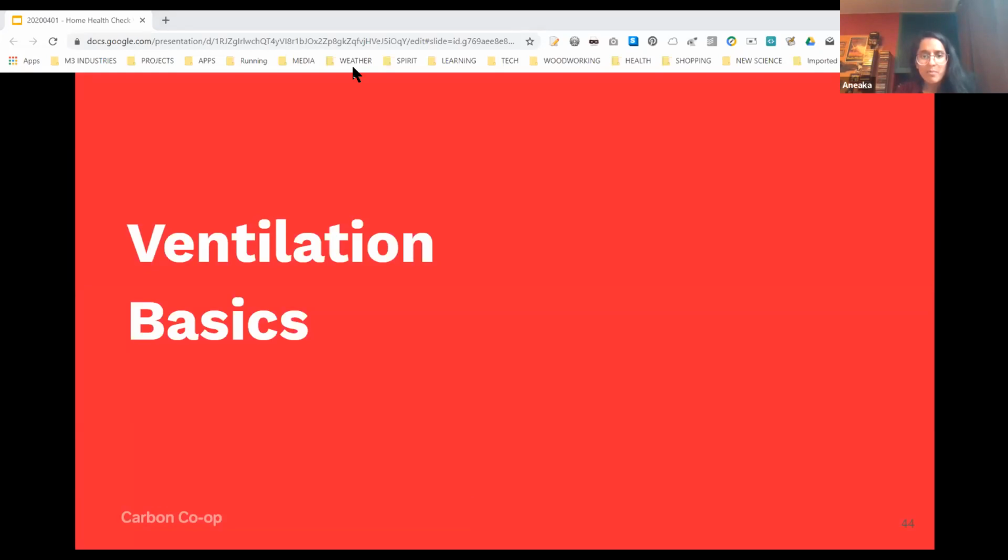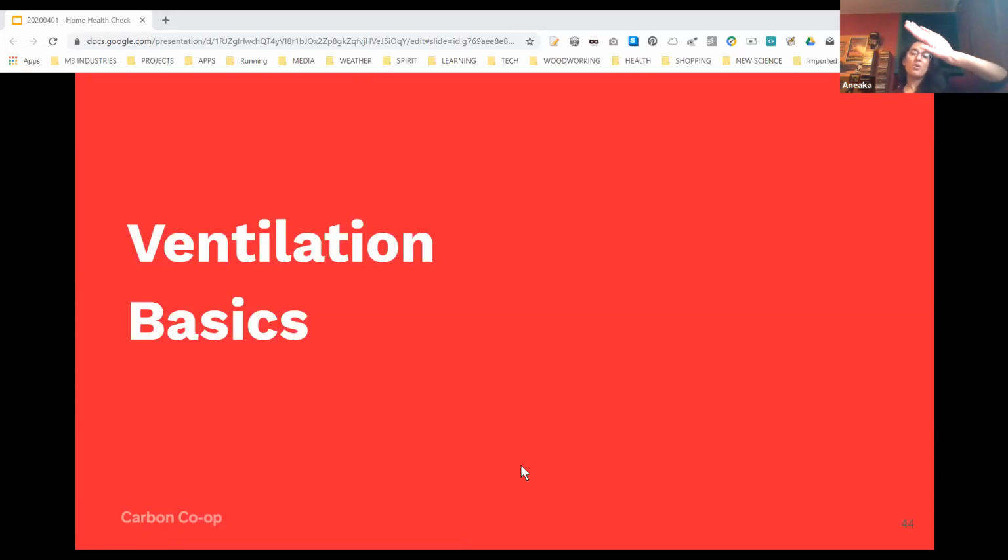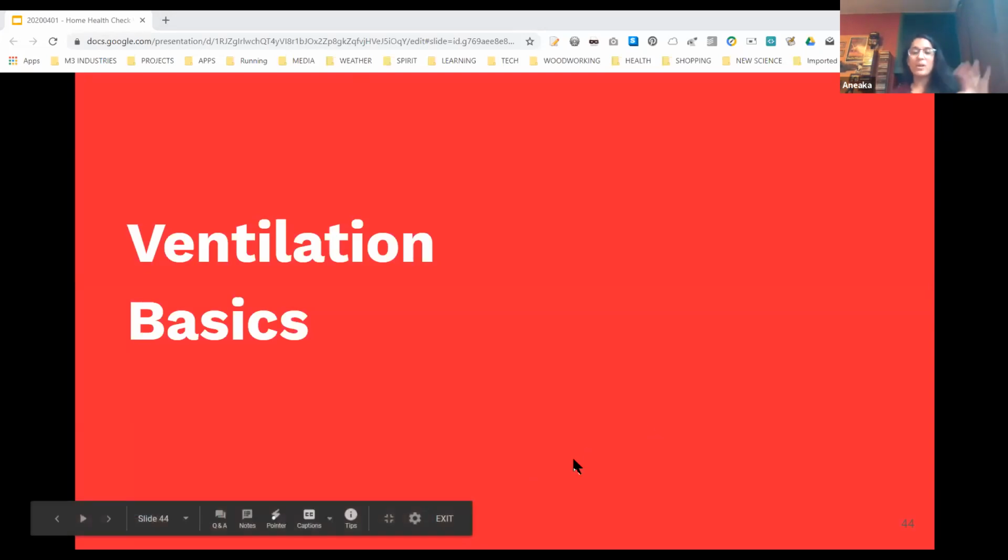There's a question here about mold growth where the ceiling meets the walls, caused by a ventilation gap when laying loft insulation. That is an interesting one. Something you can do is put internal wall insulation along that junction between the wall and ceiling. I couldn't give you too many details about that now, but there are ways that you can cover that area. I don't know if that answers your question.